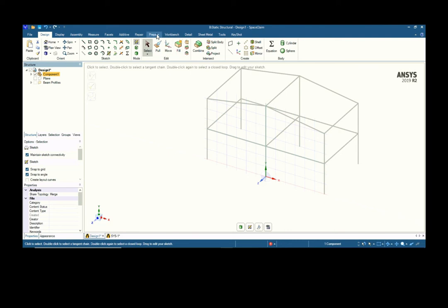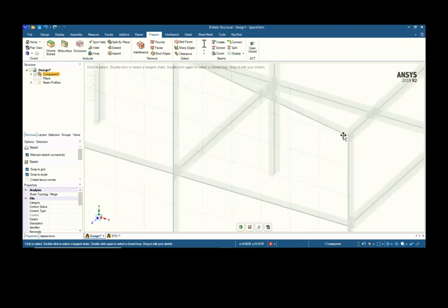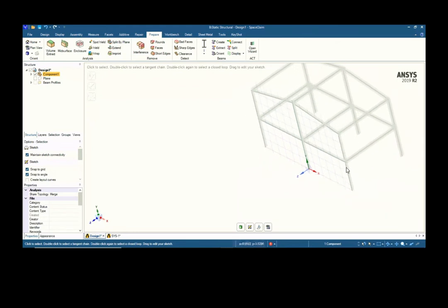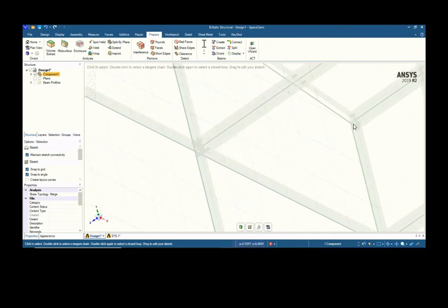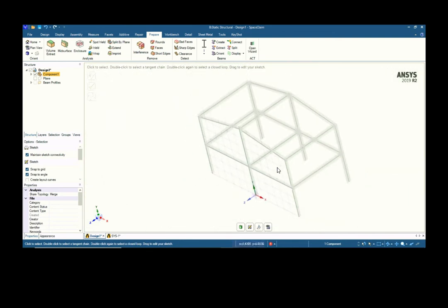But then if you go to prepare, display, solid beams, again you will see that this is under I-beams. It's not really I-beams. So you have to, again, orient it. So this is I, but not this one. The sixth line also has to be correct, the orientations.